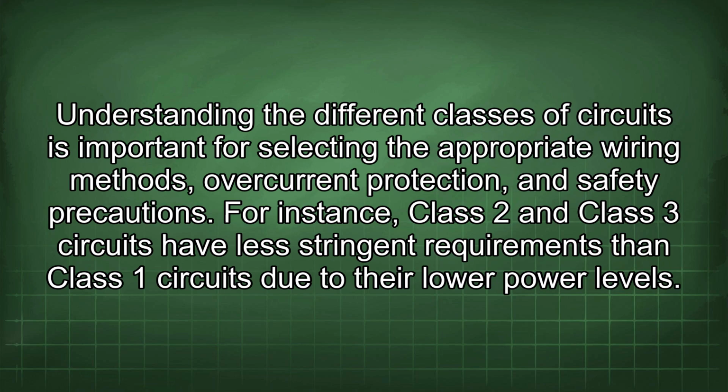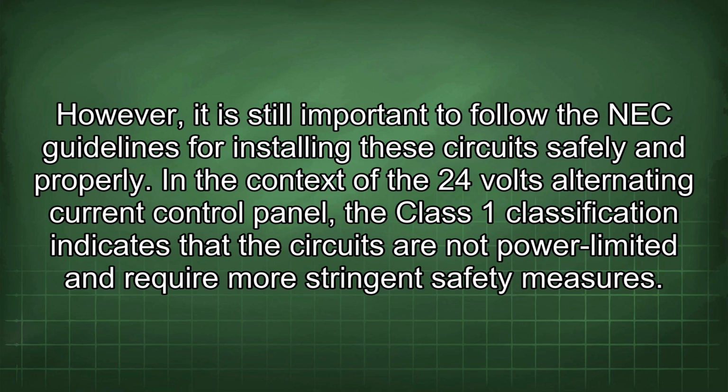For instance, Class 2 and Class 3 circuits have less stringent requirements than Class 1 circuits due to their lower power levels. However, it is still important to follow the NEC guidelines for installing these circuits safely and properly.